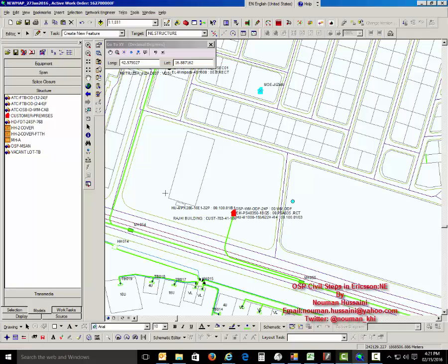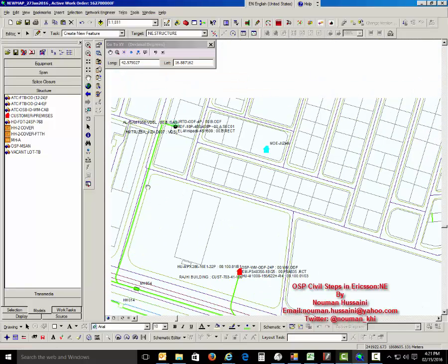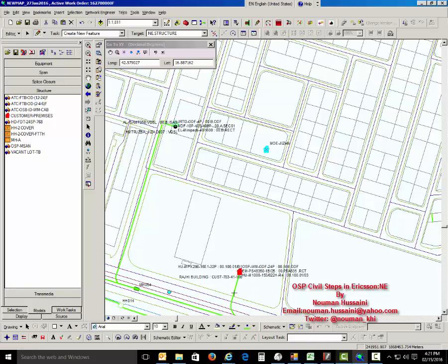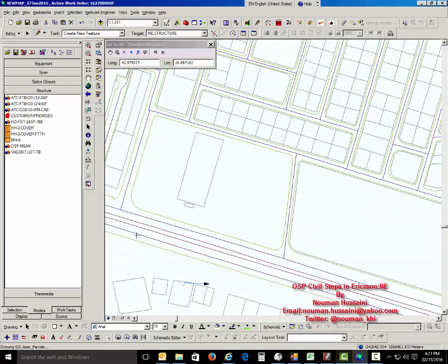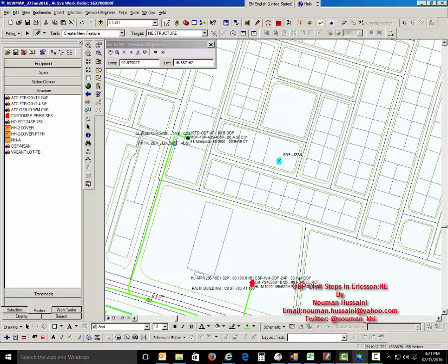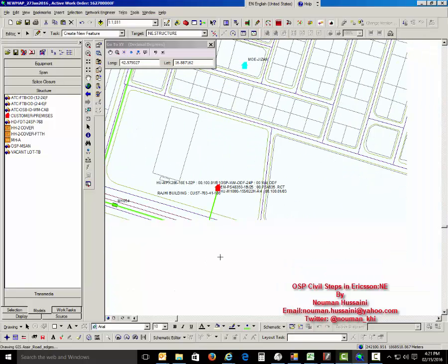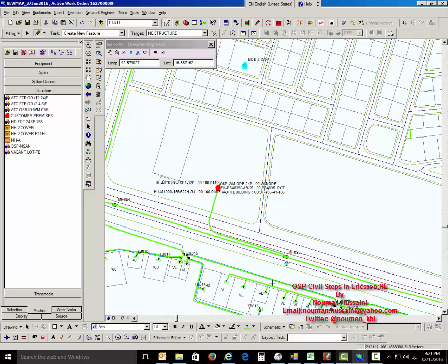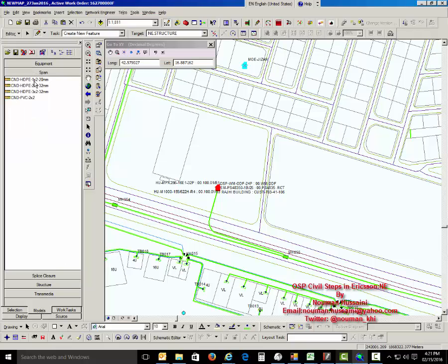Now what we will do, we will locate according to the information provided by our surveyor what is the nearest manhole or handhole from where we have to take new ducts to our customer. Also our surveyor or the project manager will tell us that after how many meters or at what turning we have to provide a two cover handhole, because if there are two 90-degree turnings on the way, then we have to provide at least one handhole, otherwise cable pulling is not possible.